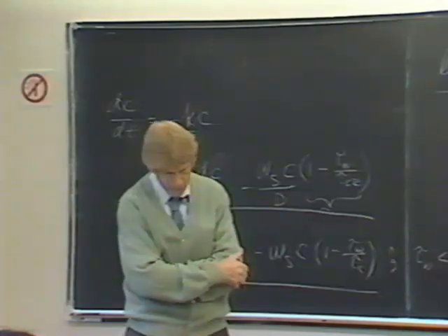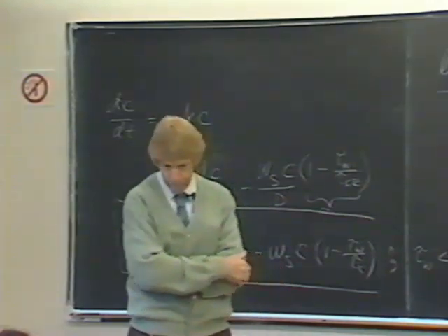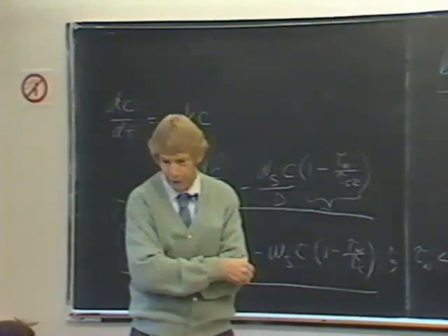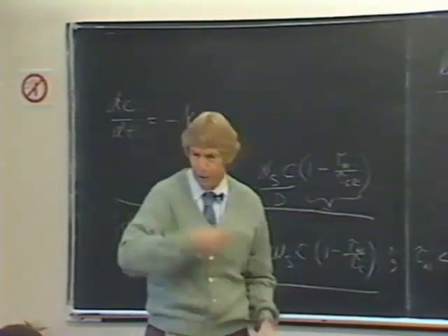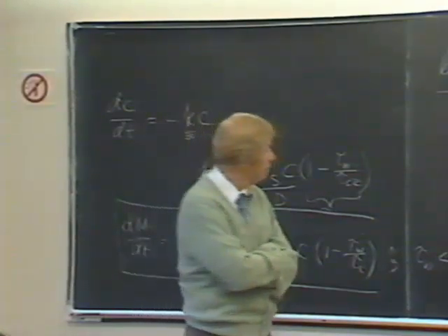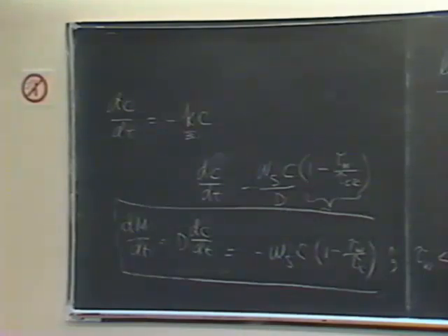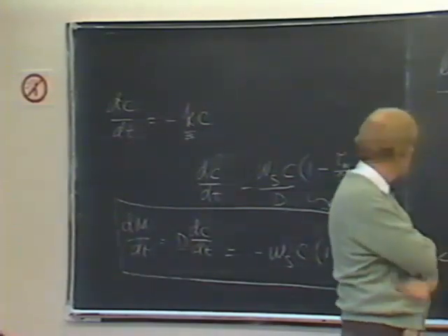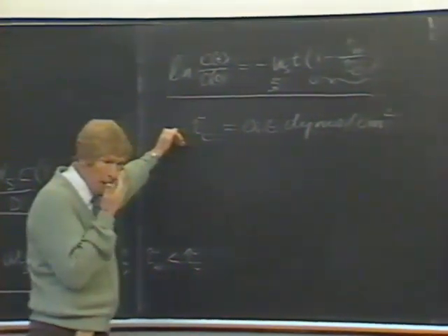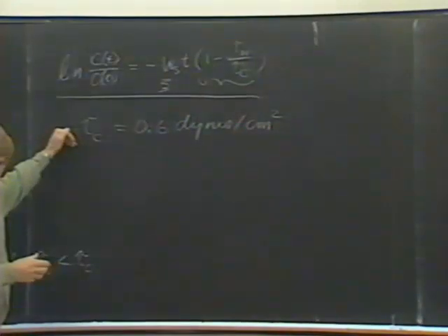Probably the greatest single factor was the shear stress on the return line pipe, on the walls of the pipe. And it was kept close to that on the bed, so that it was minimal. It appears that the aggregates weren't broken up in the pump. They were broken in the viscous layer next to the walls of the pipe and the viscous layer on the bed. That I'll explain in just a minute.